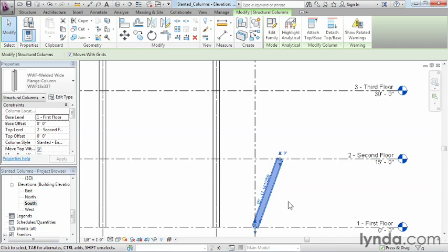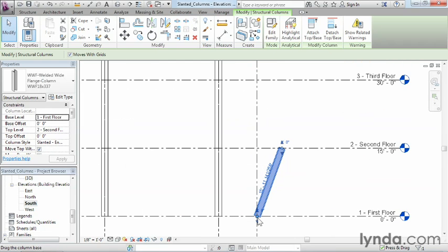In this case, though, I just know what the distance should be away from our building. Now, I know that the base is in the right location because that's where I put it on the structural grid. In this case, it happens to be 8'6" off the center of this column. But I want the top of this to be 12'6" away from the center of this column. So in order for me to do that, we're really going to have to place a dimension in here.